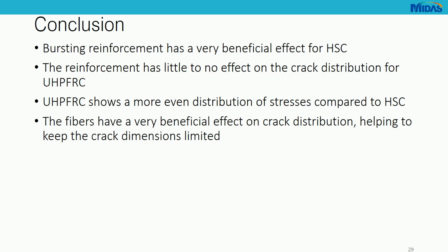And ultra high performance concrete has a more even distribution of stresses, both in the concrete mass and in the reinforcement. And we have concluded that the fibers have a very beneficial effect on both the crack distribution and the stresses.